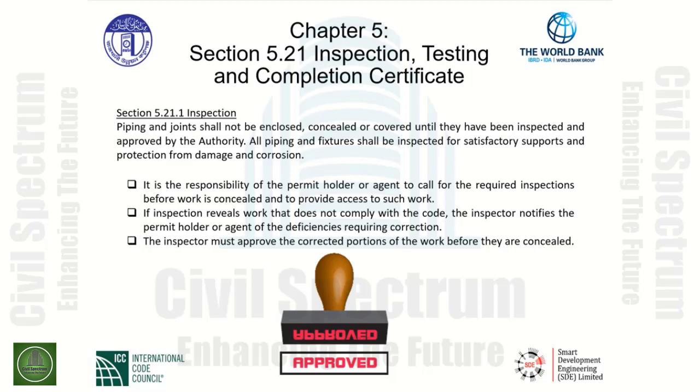The fittings have been made up according to proper installation standards, the correct size of pipes according to the construction documents is what we look for out in the field, and the bedding as well as the depth of the pipe accordingly.